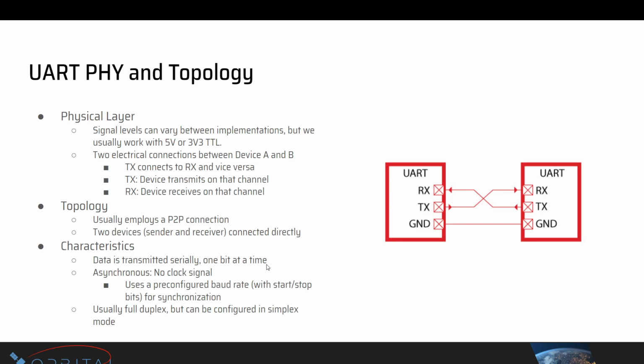So if you're using your laptop to read data over UART from the RM46 and you have it connected, your application would usually ask you what to set the baud rate to, and you would set it to whatever baud rate the RM46 is using, so that you can make sure it's able to synchronize itself properly.